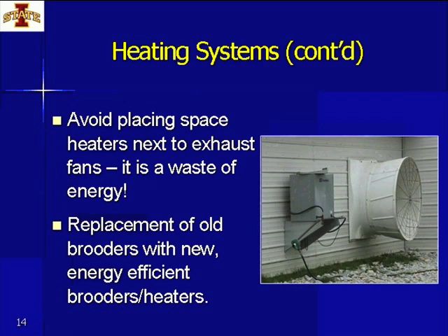This shows how things should not be done, in my opinion. I think we touched on that a little bit too. So you can see the heater placed next to the exhaust fan, and it is a challenge in some cases where you have a large barn and are trying to use a few space heaters to distribute that heat evenly. So there are some things that need to be done for us to more efficiently utilize the heater in this case.